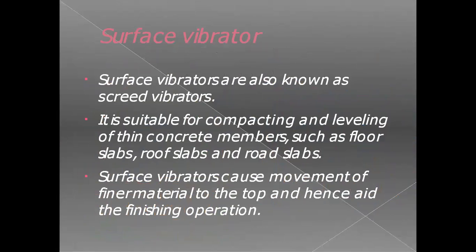Surface vibrator. Surface vibrators are also known as screed vibrators. They are suitable for compacting and leveling of thin concrete members such as floor slabs, roof slabs, and road slabs.